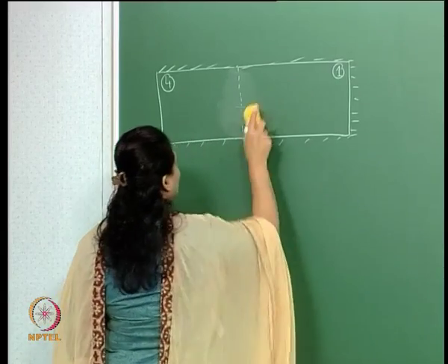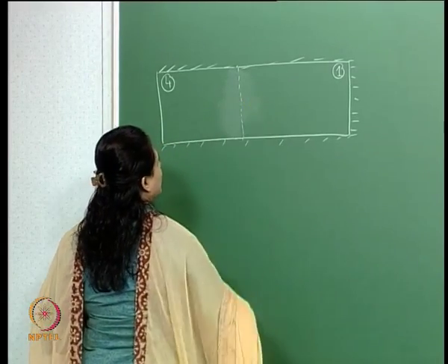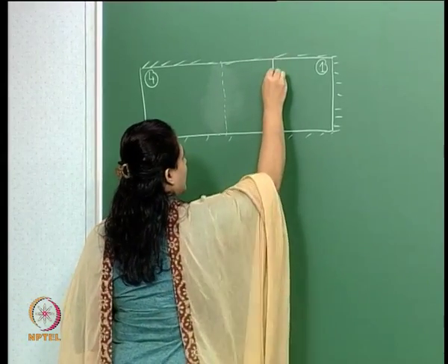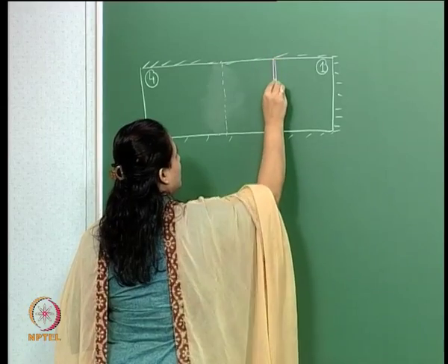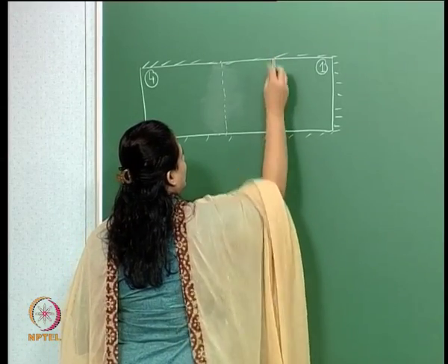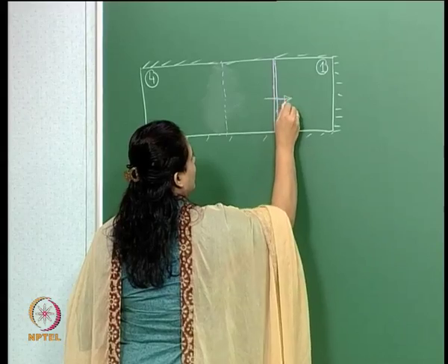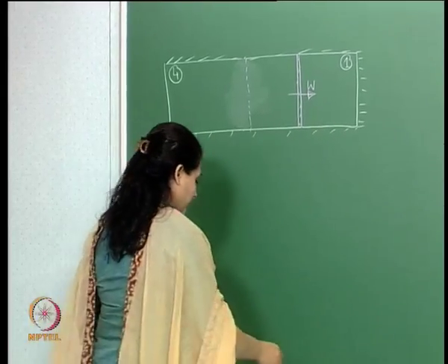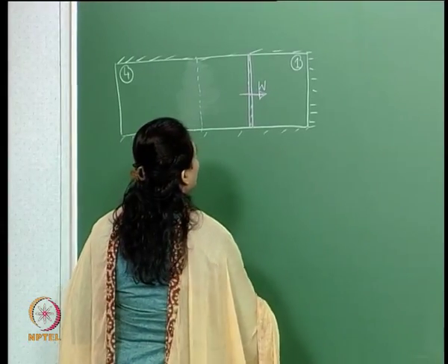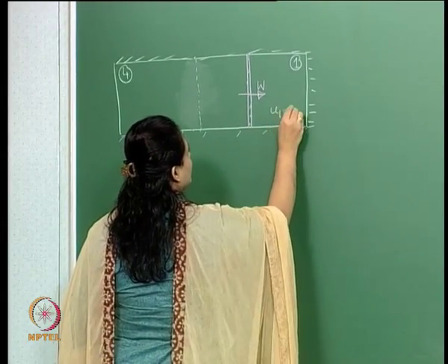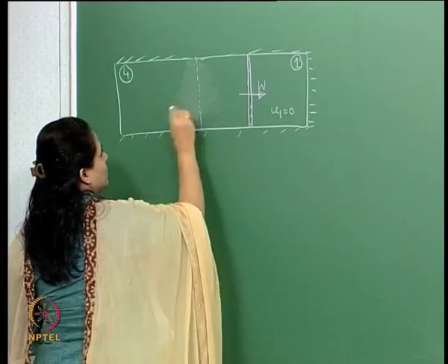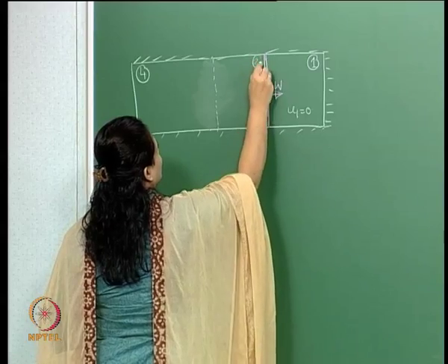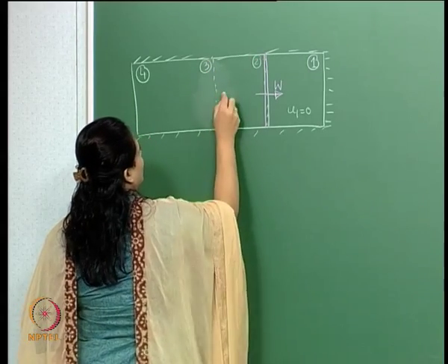What we essentially have when we break the diaphragm is a normal shock, which starts moving into quiescent flow, and this induces mass motion in this region. We're going to call this region 2.